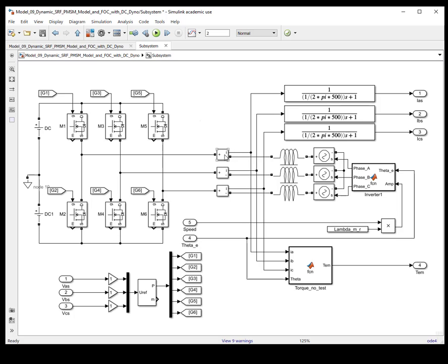And we're going to be measuring the inline or the phase currents that are applied to the motor. In practical applications, you tend to have low side or high side shunts. You can apply the same. You can place a resistor or place a current sensor on the low side or high side, and then you can measure those voltages, then use them for your control as well.